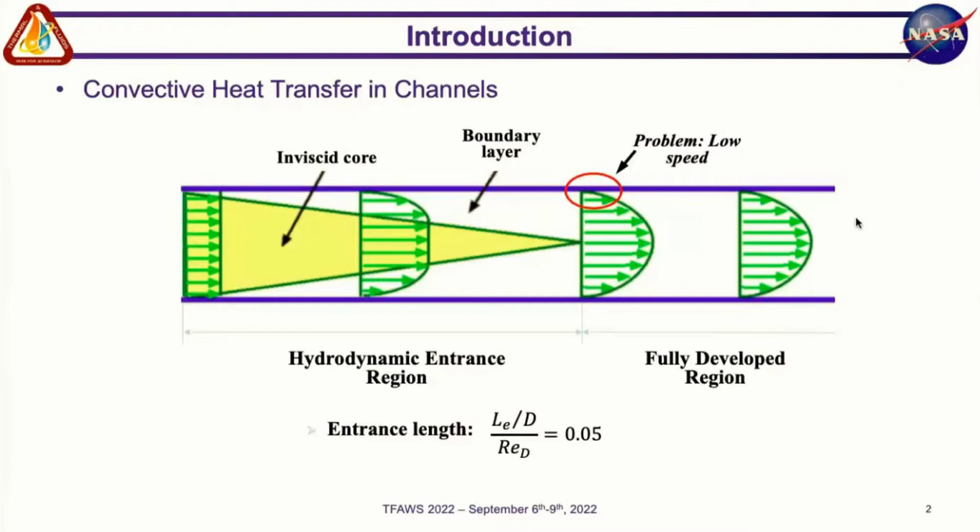No matter what kind of flow distribution you have at the inlet of your channel or heated section, you are going to have boundary layers developed along the surfaces of your channel. And it's exactly at the surfaces where your heat transfer is going to take place between the walls of your pipe or the external section of your system and the fluid that's flowing through your pipe, either to cool the walls of your channel or to heat the walls of your channel.